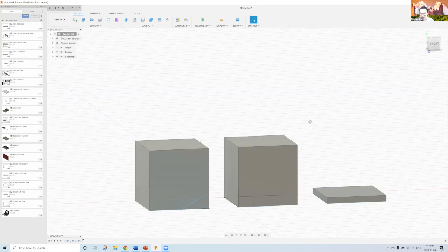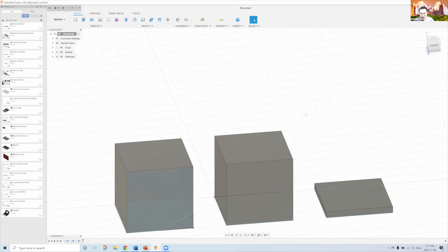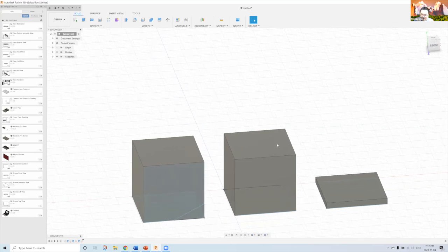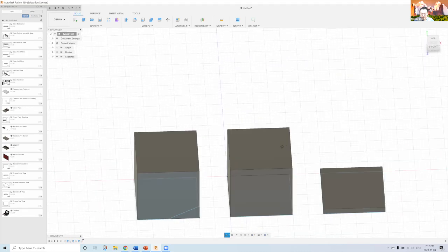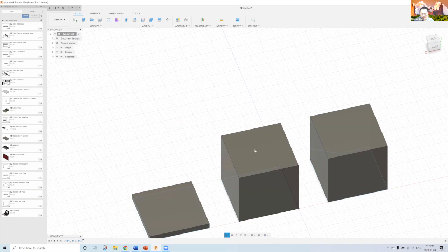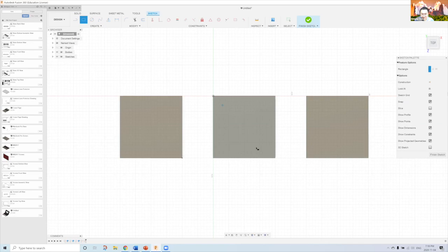Awesome. So you can see here we have a few objects. First off, one thing that I mentioned is you want to avoid printing very large blocks, right? You can optimize this object by, number one, changing the infill percentage to 15-25%, or you can make it hollow. Let's say you only want the outer size of this object. If that's the application, you can take this whole thing out, right?